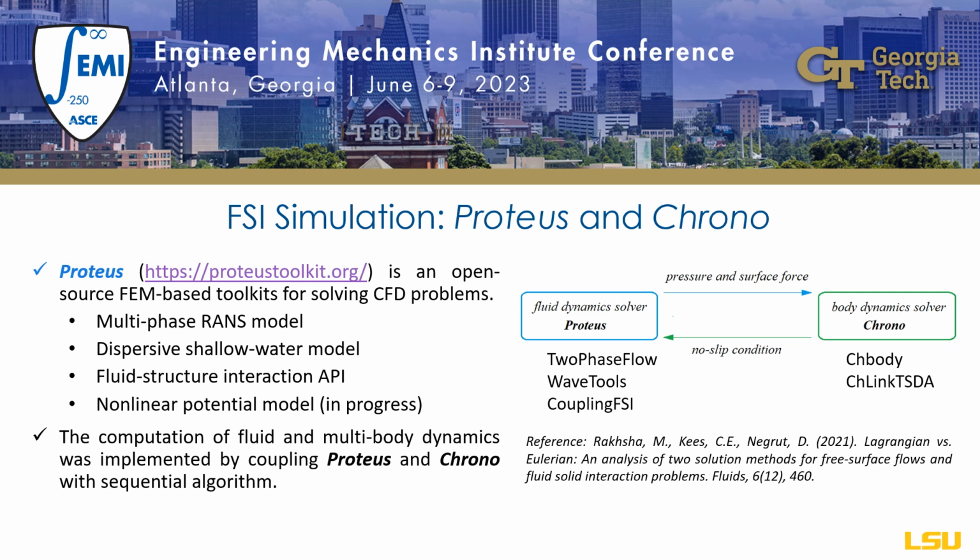And in this study, we will take advantage of another open source toolkit, Chrono, to handle the structural dynamics. We build the interface between these two packages to pass the variables so the solution can be processed sequentially. Some important modules are TwoPhaseFlow and ChBody for the fluid and structural dynamic solvers, WaveTools for wave generation, ChLink for mooring modeling, and coupling FSI for variable delivery.